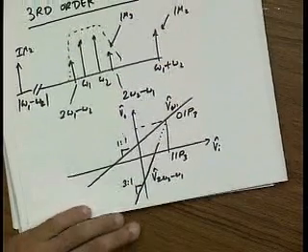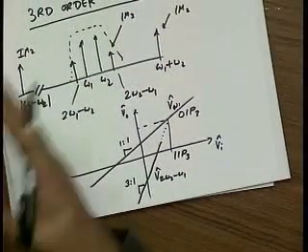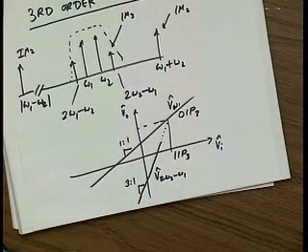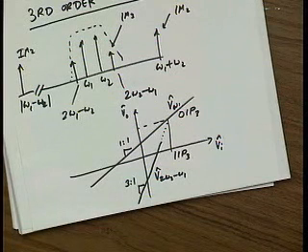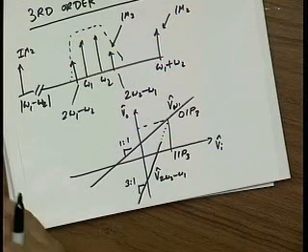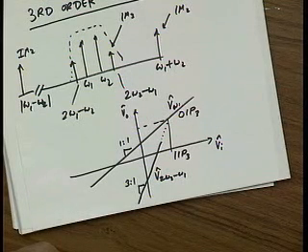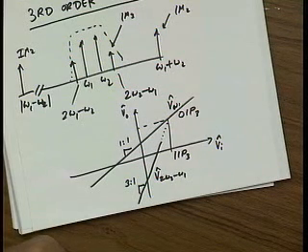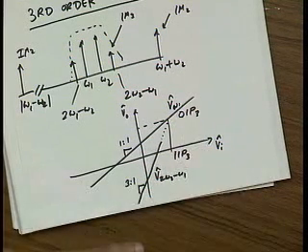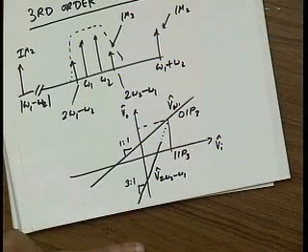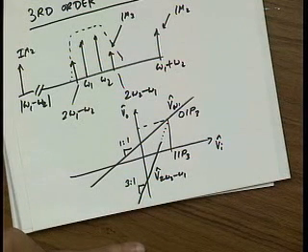And again, IP3 is the way you typically specify. If you go look at a data sheet for an amplifier, they're not going to tell you what IM3 is at some power level. What they will tell you is the IP3 point. And from the IP3 point, you can calculate basically where you can operate your amplifier. You know, how much distortion can you tolerate? Well, let's say the IP3 point arbitrarily is at 0 dBm. Let's say you need 100 dB of IM3. What's the maximum input power that you can put in? Anybody?